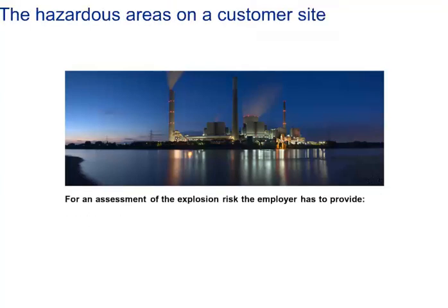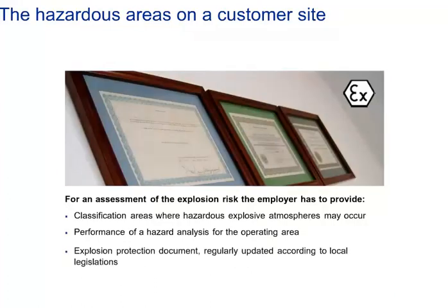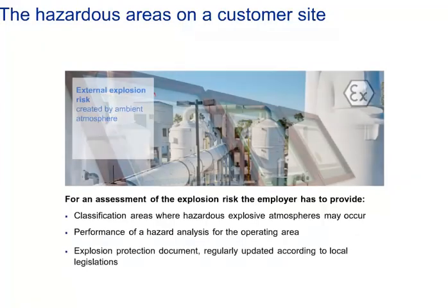For an assessment of the explosion risk, the employer has to provide classification of areas where hazardous explosive atmospheres may occur, performance of a hazard analysis for the operating area, and an explosion protection document, regularly updated in accordance with ATEX 137.